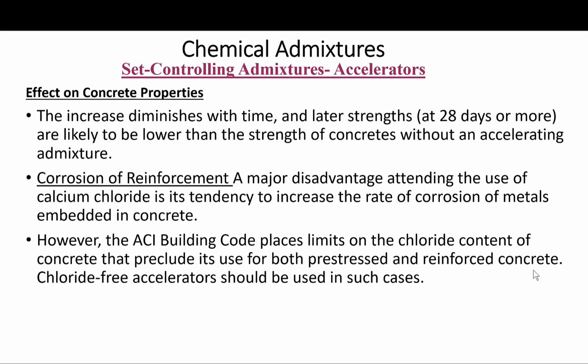Also, calcium chloride can discolor concrete and should therefore never be used in architectural concrete. As I said, really, many variables, and every aspect of your concrete should be investigated when it comes to these admixtures. You never know what they will do. I'm sorry to say this, it sounds like a general layman statement, but this is the case.